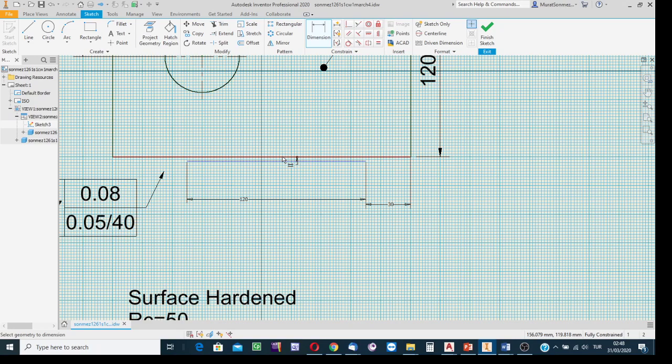There is a requirement to satisfy. Well, don't worry about the line type. It is not in chain line quality yet. Whenever you draw something in sketch mode in Inventor, it is going to be a thin continuous line. It comes from the default configuration of the software.